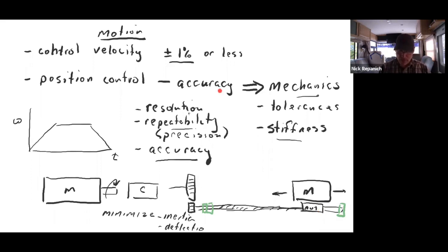accurate system as any motor or motion control that you pick, because you can really screw it up bad by going and buying a cheap motor control coupler instead of a motion control coupler. Heavy inertia and lots of wind up because it has a rubber piece in the middle. Boy, we don't want a rubber piece in our transfer function. We wish we didn't even have a transfer function. We wish the motor was the load. And in fact, that's what you start to see more and more.